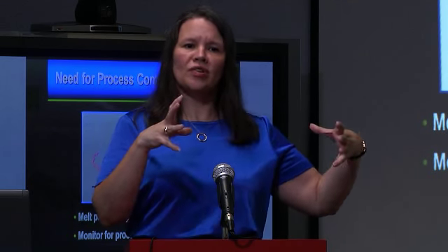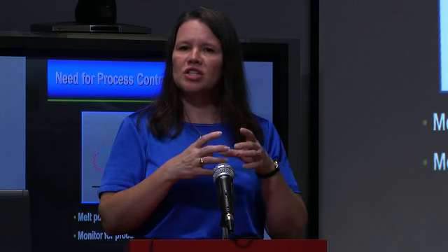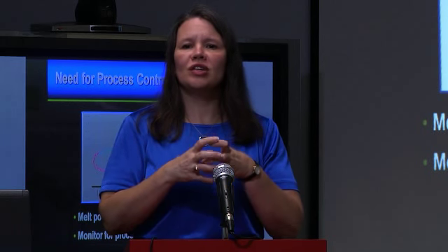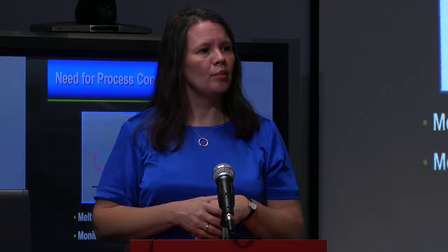And so if we don't change any of our properties, we've measured how that melt pool gets larger with time. Now that we've got a measure for how things are changing, we can go in with some algorithms if we understand what the process interdependencies are. We can go in and take those melt pools and try to force them all to look the same from one layer to the next. If we can keep the melt pool looking the same from one layer to the next, then we believe that our temperature conditions are continuous from one layer to the next, which will give us much more uniform properties and much more repeatable properties from one part to the next.